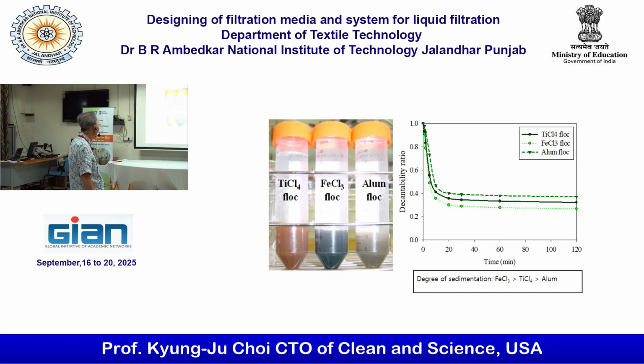When you look at the decantation ability ratio and time for the different coagulants, you'll see the decantation ability ratio is much better with the aluminum floc than with the FeCl3 floc.